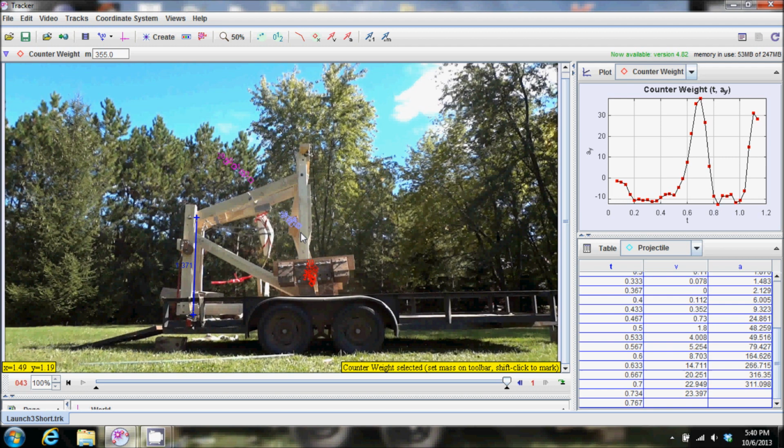And at the bottom here, it's really pulling pretty hard. And like I said, about 13 kilonewtons, 3,000 pounds pulling back. Now I get to divide that. Half of it's going up here, half of it's going down here. I looked up the coefficient of friction. Steel on wood is about 0.2. And now I've waxed the wood. I couldn't find a coefficient for that. I think that's helping me quite a bit compared to the 0.2. So if it was 0.2, that would be about 5% of my energy would be lost just right there rubbing. So I figured probably 2%. I think the wax is making it twice as slippery.